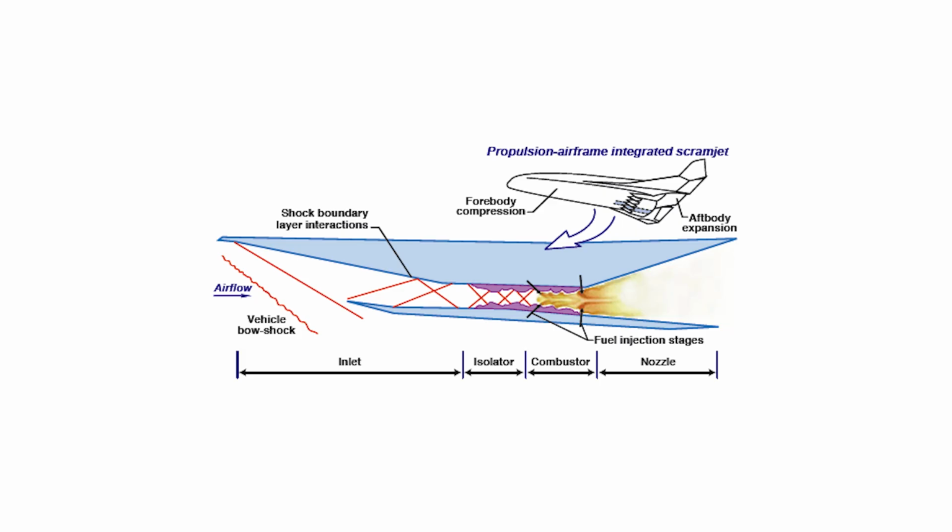For example, for a scramjet flying at Mach 5, the airflow entering the combustor would nominally be Mach 2. One of the major challenges in a scramjet engine is preventing shock waves generated by the combustor from traveling upstream into the inlet. If that were to happen, the engine may unstart, resulting in loss of thrust, among other problems. To prevent this, scramjet engines tend to have an isolator section immediately ahead of the combustion zone.